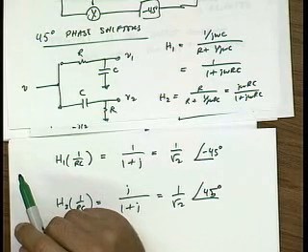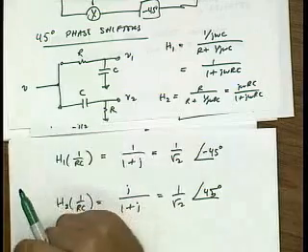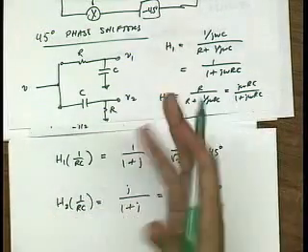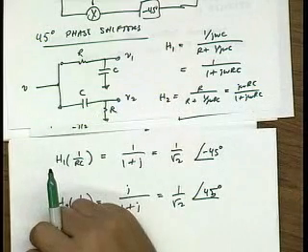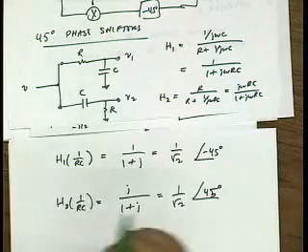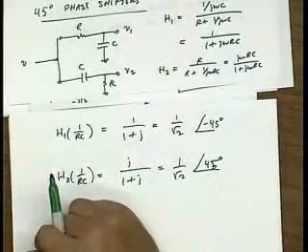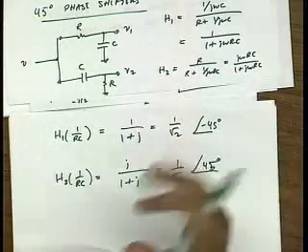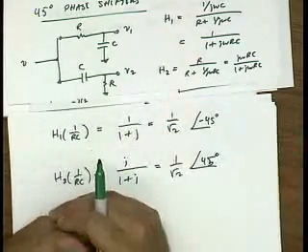Okay. Well, because to get a 90-degree phase shift would require a really long piece of wire. That's quarter wavelength. So if you think about it, at a gigahertz, the wavelength is on the order of centimeters on chip. So you need a quarter of a centimeter to get 90 degrees phase shift. No, but it's a totally valid question. That's how you do it at really high frequencies. If you go to really high frequencies, you basically use transmission lines to build phase shifters. And actually, transmission lines are superior because it's a real phase shift, right? It's a real phase delay.